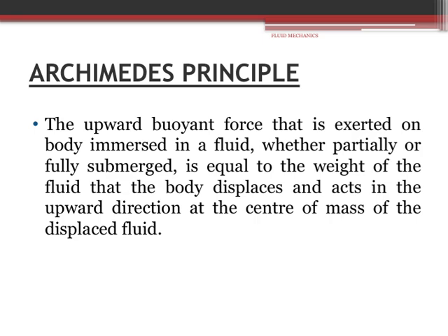When a body is immersed in a fluid, whether it's just partially submerged or completely underwater, it experiences an upward force. This is what we call the buoyant force. Now, an important point to remember is that this force isn't just arbitrary, it has a specific magnitude. It is exactly equal to the weight of the fluid that the body displaces. So, if you imagine placing an object in water, the amount of water it pushes aside determines the buoyant force acting on it. And this force acts upward, right at the center of mass of the displaced fluid.